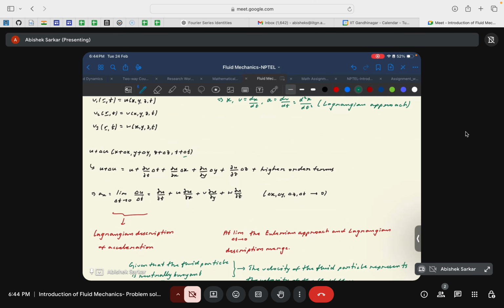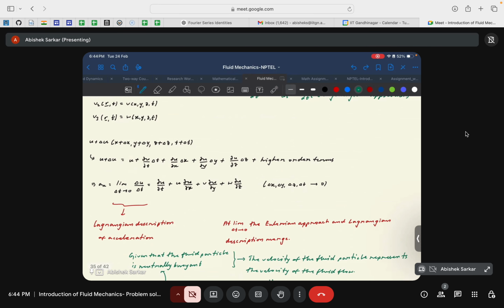Of course it has varied from time t to t plus delta t. Now to find u plus delta u, we can again use the Taylor series expansion. So you can write something like delta u is equal to dou u by dou t times delta t, plus dou u by dou x times delta x, dou u by dou y times delta y, dou u by dou z times delta z. If I move very fast, I'm very sorry.